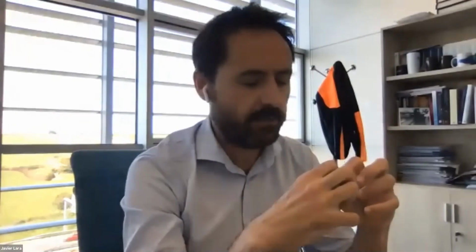Well, the reason for doing that is because the method itself is not prepared for the interaction of two solids. The overset method was developed only for floating objects. So there is no interaction of the mesh when it is moving all around the domain; it is not interacting with the boundaries or with another solid.